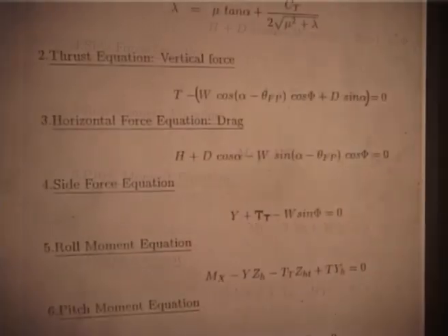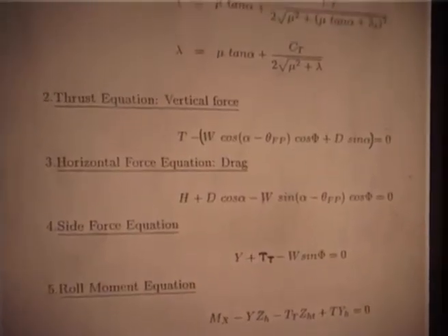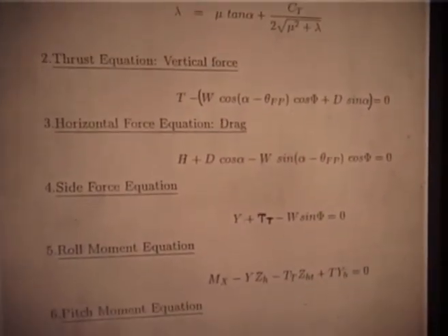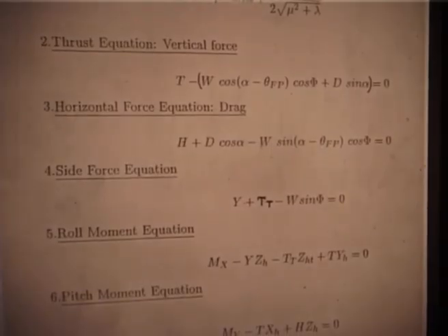Because where is the flap equation coming in between? Okay. Because the flap equation is sitting somewhere, because all these thrust, H, Y, Mx, My, they all are dependent on flap response. Okay. Now, flap response we approximated as the first harmonic, beta naught, beta 1c, beta 1s, that is all, the rest of them we neglected. So, all these expressions require flap. So, you have to now introduce the flap equation in between.